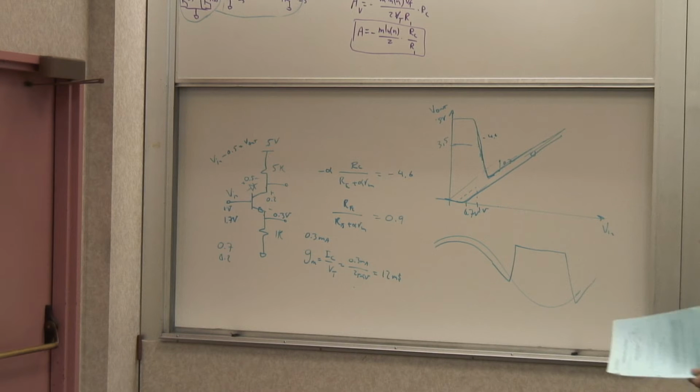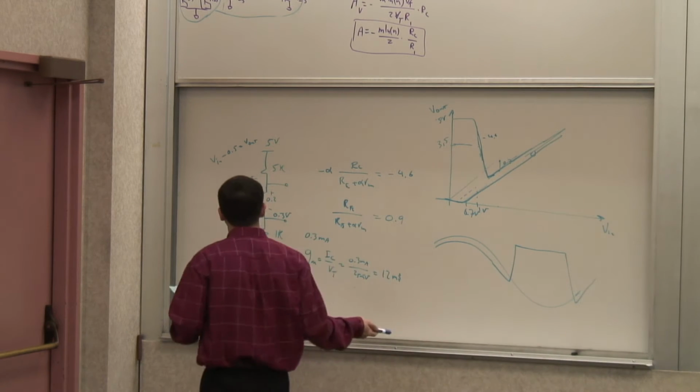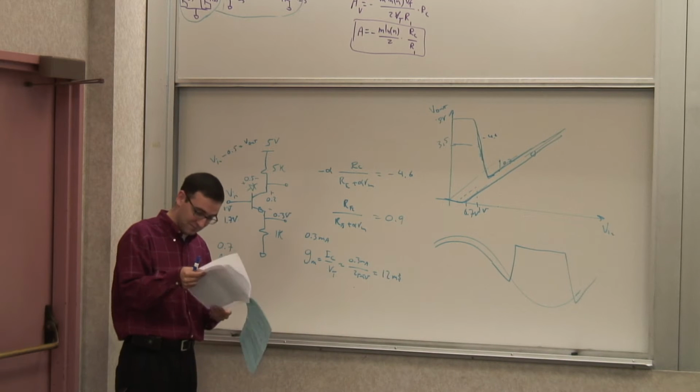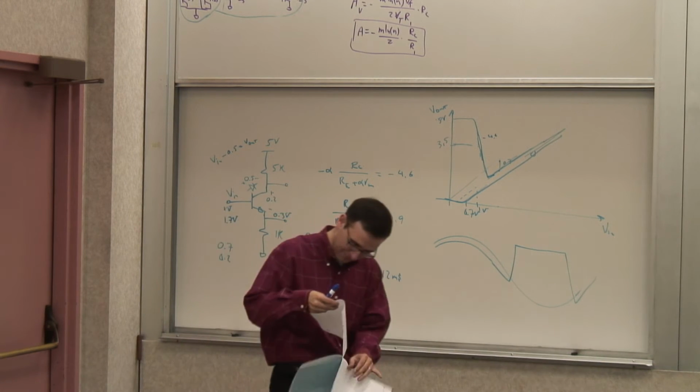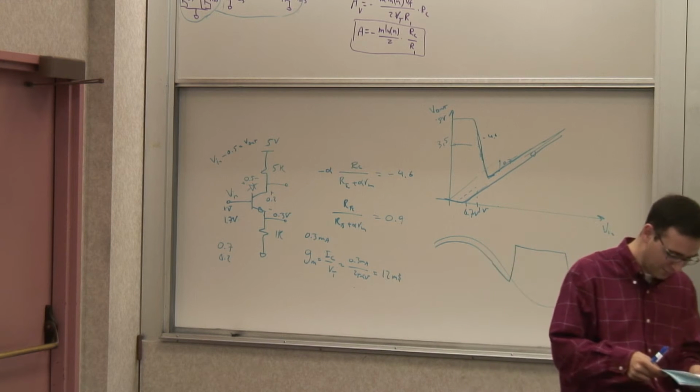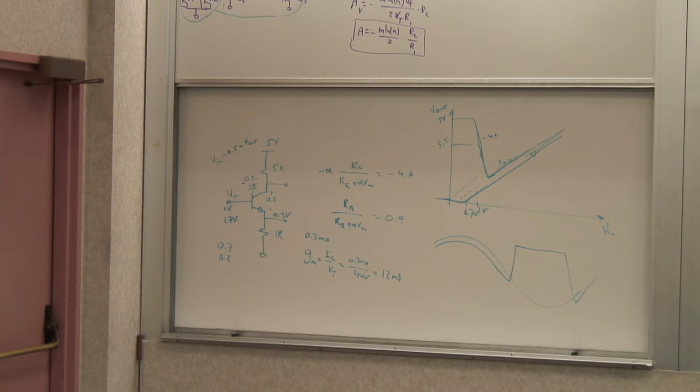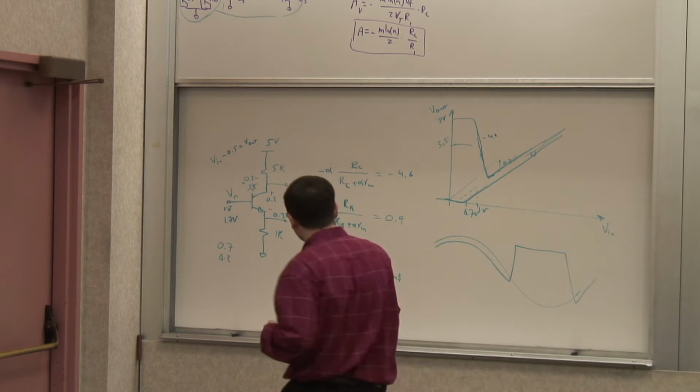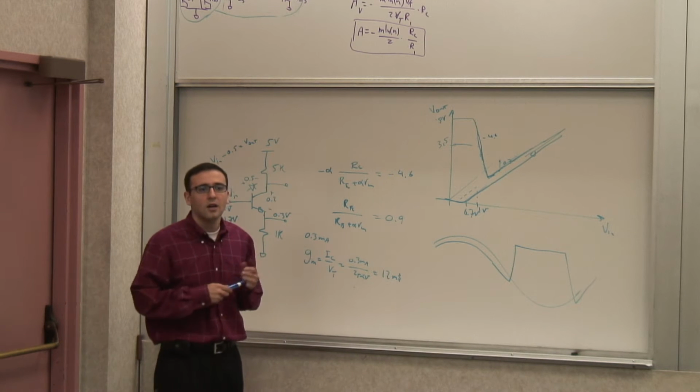The tricky part of it was the fact that the transistor could go into saturation. I tried to give you a hint by saying, hint, be mindful of operation in regions other than forward active region, FAR. But that's actually how you can get a non-monotonic response. It's not a great way to get a non-monotonic response because there will be a huge base current at that point. We can do some of the problems later on if you want, but I think we should have a solution. Any other questions?